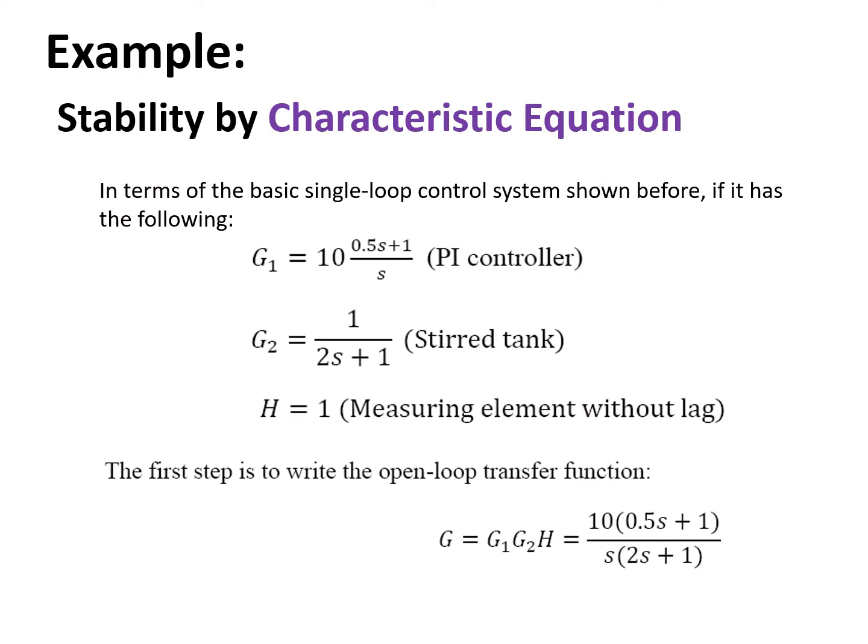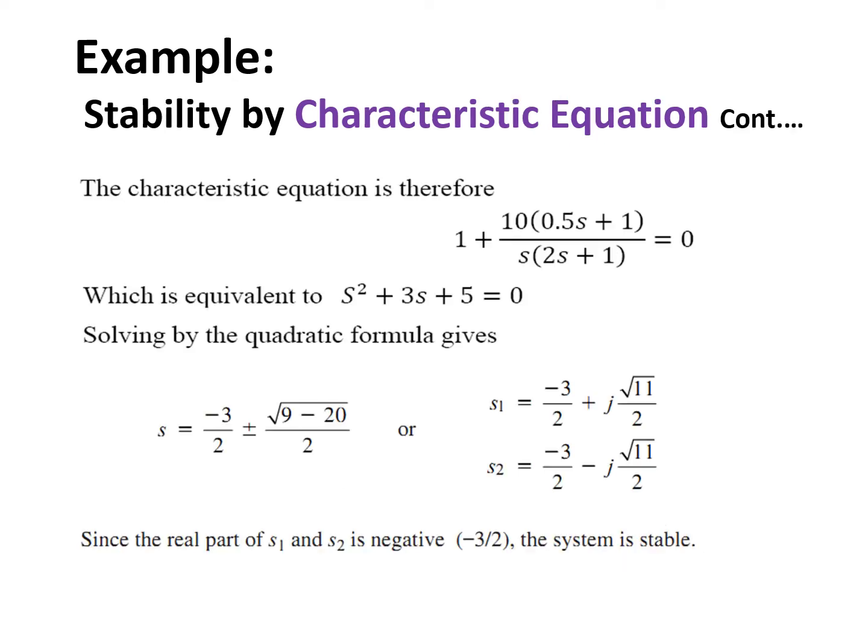This is an example given for a second order system where we get the characteristic equation, and looking at the characteristic equation, we look at the roots and then determine whether they are on the right or the left plane. Okay, this is an easy, fast way, but as you can see, it depends on the number of roots. If there are a lot of roots, then it'll be quite a tedious method. Of course, we can use MATLAB to get the roots, but there is also a specific and organized way of checking the roots from our next topic, which is the Routh stability analysis method.